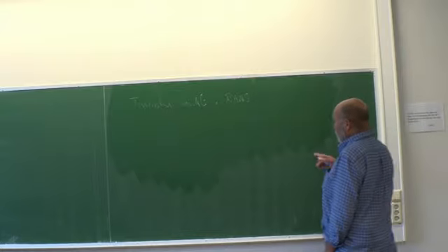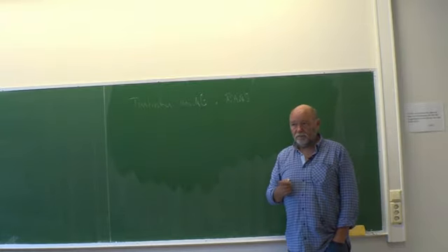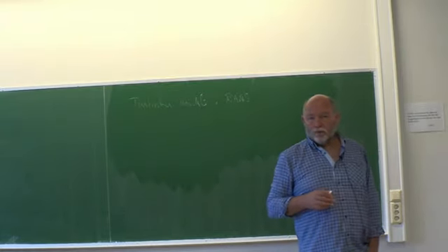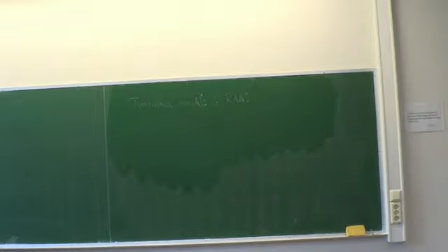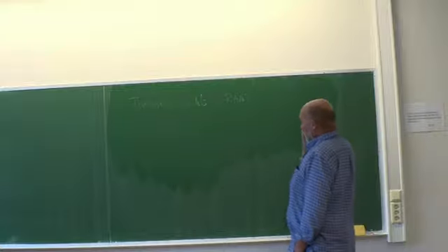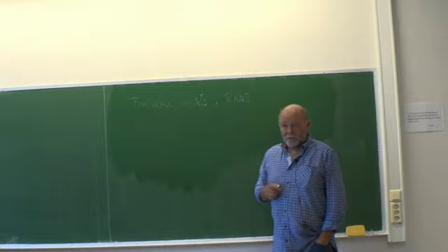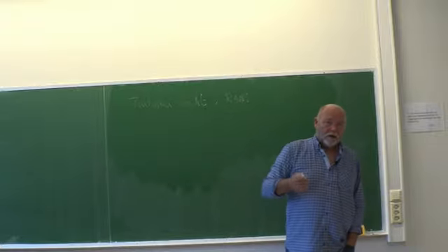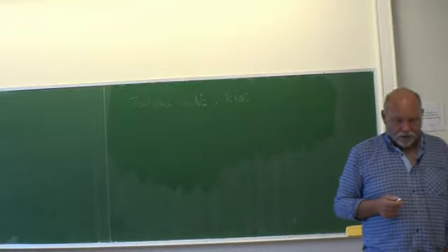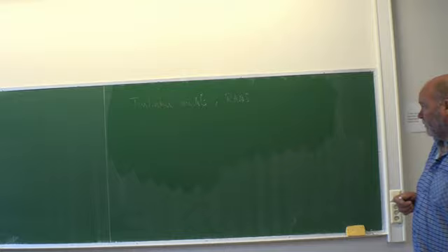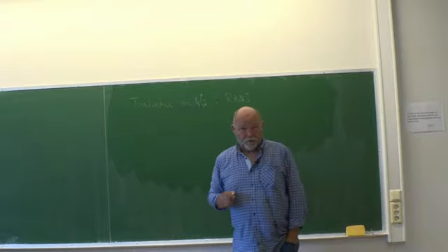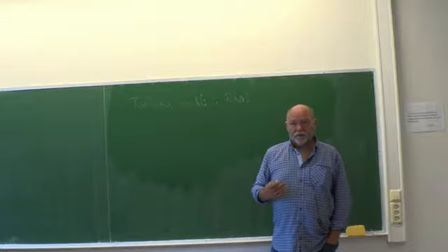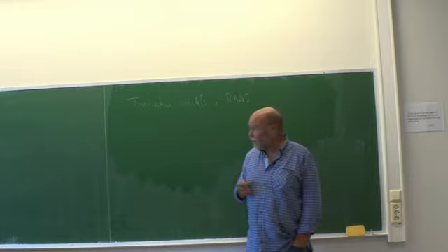We have something called Spalart-Allmaras as a 1 equation model, 1 transport equation model for the eddy viscosity. That's also something you should be aware of. For now, we have just played with typically k epsilon, k omega. So that one is something definitely that should be part of your report. Convince me that you know how to use these.